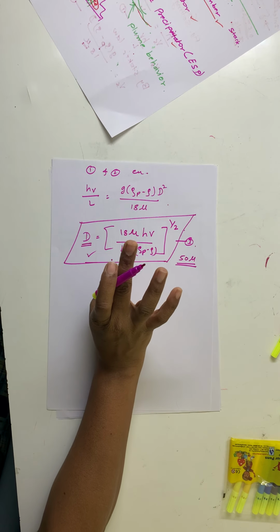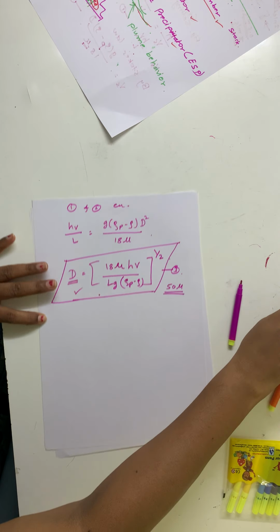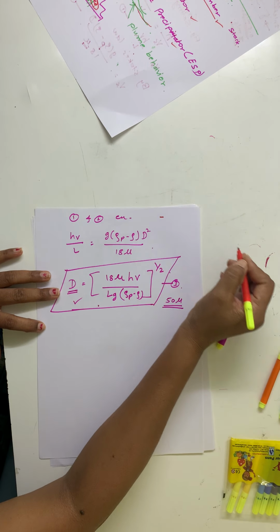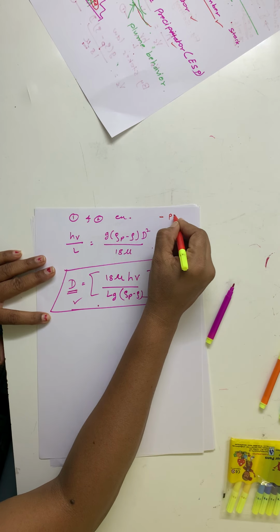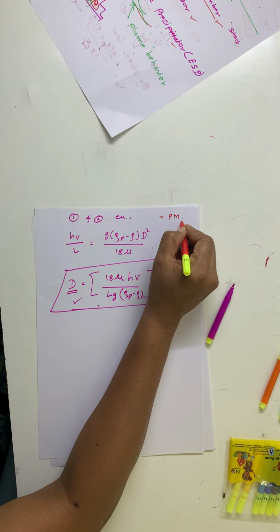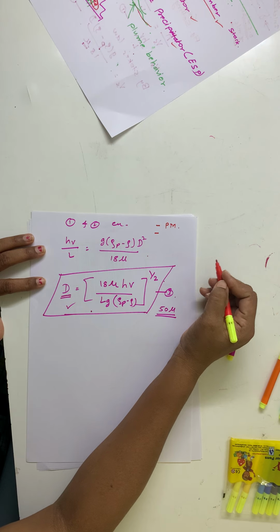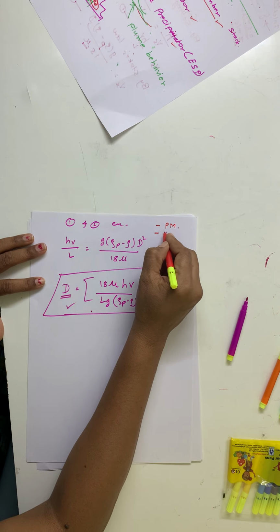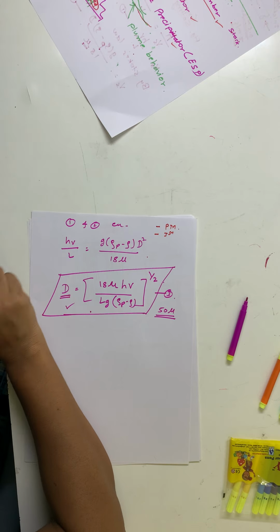Once again I will repeat the important 2-3 points about the gravity settling chamber. The first point: this equipment is used for the removal of particulate matter or dust, not for gas. Second, this equipment can be used as the first equipment in a series, because it removes the larger size particles.